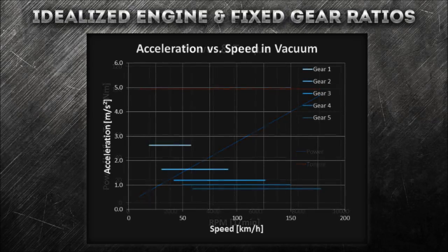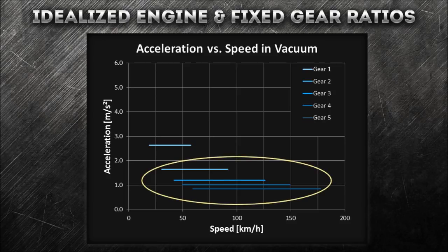With just a single fixed gear, a car with a combustion engine would not perform well because it limits the range of speeds a car can drive. To illustrate this, we take the idealized 100 Nm engine as example, accelerating a car from 20 to 60 using the 2000 to 6000 RPM range in first gear. Acceleration remains flat throughout that gear. We also see that acceleration in higher gears in the same rev range are lower overall.